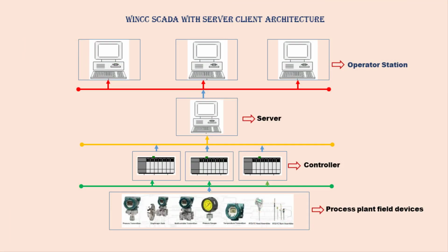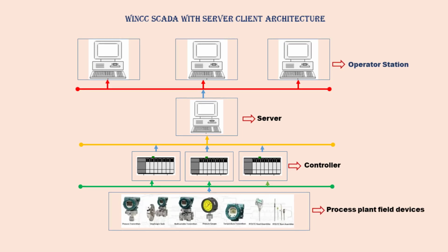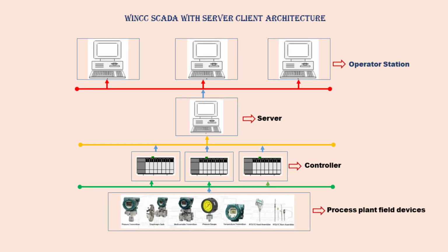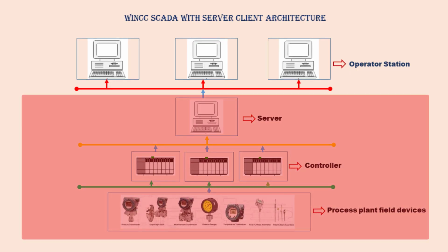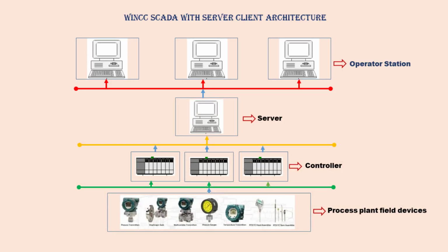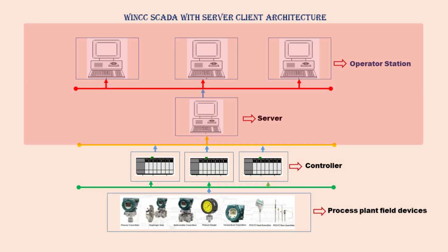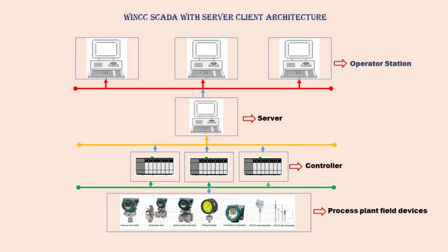For large industries, it becomes necessary to operate the plant from several operator stations by different operators, or often data from different systems have to be collected and evaluated centrally. The use of a WinCC client-server system is recommended for this purpose. The WinCC server handles communication via the process bus with the system controllers and provides the user data and visualization data for the WinCC clients. This makes it possible for the system to be operated simultaneously from several operator stations by different process operators.